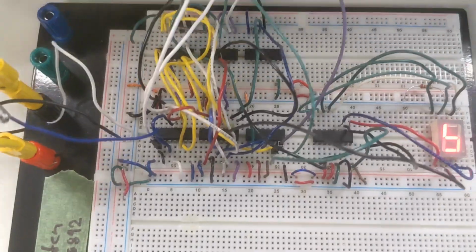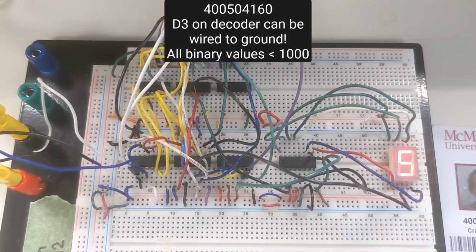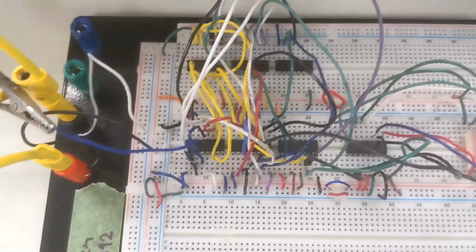Yep, and keep in mind our student number, none of the digits go above 7, so we could get away with using only 5 flip-flops instead of the 6 you'd normally have to use.